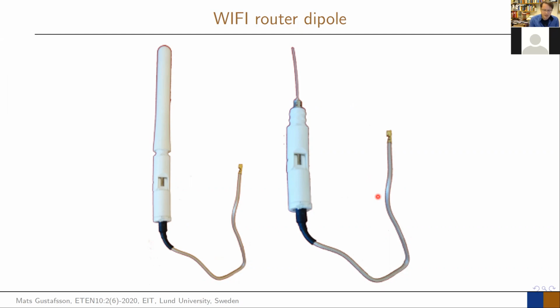And they are this sleeved dipole, where you can see the wire sticking up. If you were drawing the rest of this picture, you would have metal going down there also. So you will have a dipole with a current around this structure. What you have here is the end of the coaxial cable, a really, really tiny open coaxial cable with a diameter of approximately 1 millimeter, connected to the electronics and the signals that can be transmitted. So these are very, very common antennas, used for many different things. They exist almost everywhere, I would say, dipole antennas.